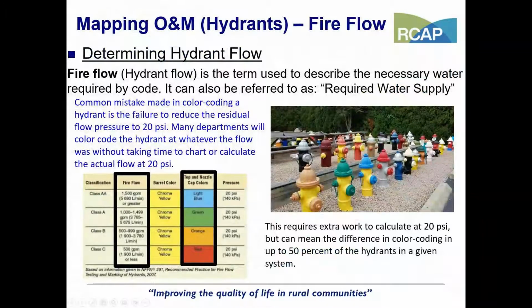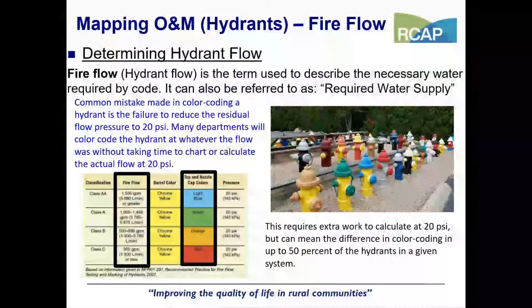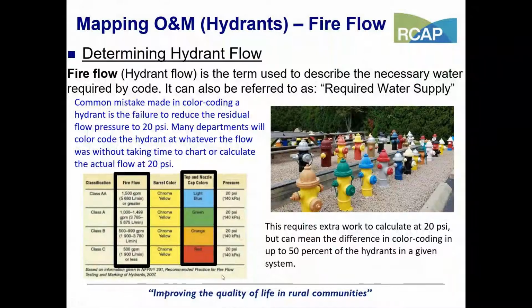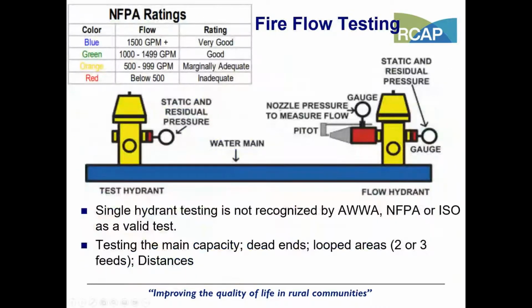So if we determine the fire flow, we can also color code it. How many people in here color code your hydrants? You can use that raise your hand reaction. This is a really good way to communicate with the fire department and just with each other yourselves as a utility. And maybe eventually the public if they realize what these colors stand for. Or if you're a system and you color them the color of your local high school, I've seen that too. But it is becoming more common to color code it. If you have an engineer consultant, someone coming in, they can quickly identify what that pressure rated capacity is going to be, or the flow rate capacity.